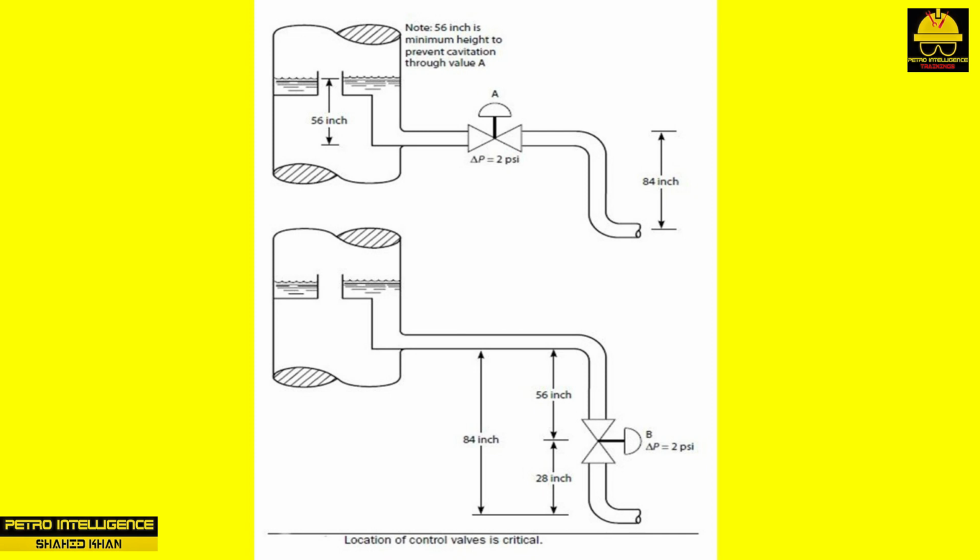Does this mean that control valves should be located well below the elevation of the draw-off nozzle? Yes. Does this mean that the amount of piping, fittings, gate valves, etc., should be minimized on a draw-off line until the line drops 10 or 20 feet below the draw-off nozzle? Yes. Does this mean any frictional losses due to external piping at the same elevation as the draw-off nozzle have to be added to the nozzle exit loss in determining the liquid level in the sump? Yes.